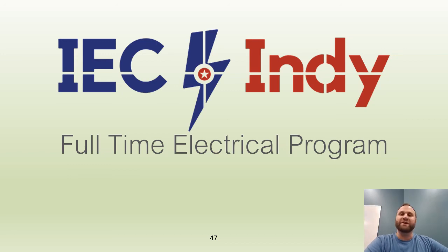Yet, for now, we still have permission to reduce the size of our neutral, so we're using less material. When I install a neutral, I install it the same size as my ungrounded conductors. But again, the code is bare minimum, right? Bare minimum for protecting people and for protecting property. That's the purpose of the NEC.